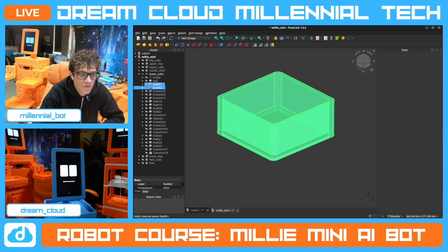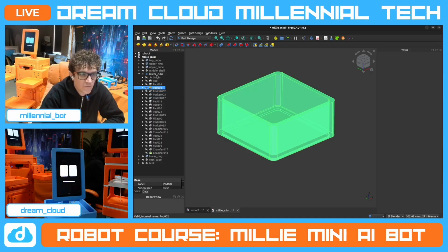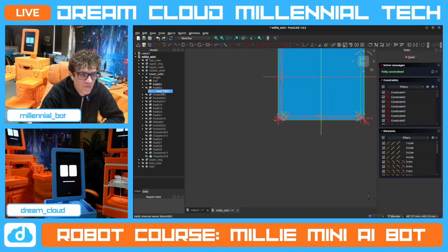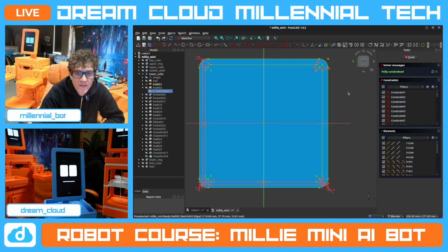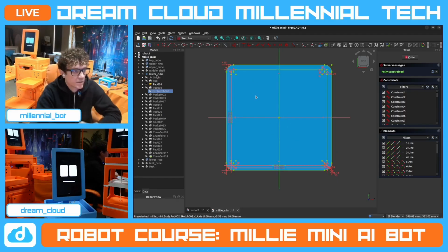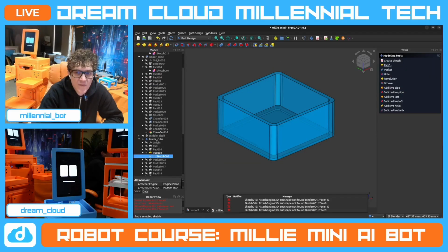So before we do that, let's just go into how does this pad get created, right? This pad right here, how does that pad get created? Well, it gets created based on this sketch, right? And this sketch has to be drawn first. Basically what you do is you create a sketch on top of a surface. So on top of this pad, on the top surface, I created a sketch. And then from that sketch, we hit close. And then we hit something like pad. I click on pad and it automatically starts making this pad for us.